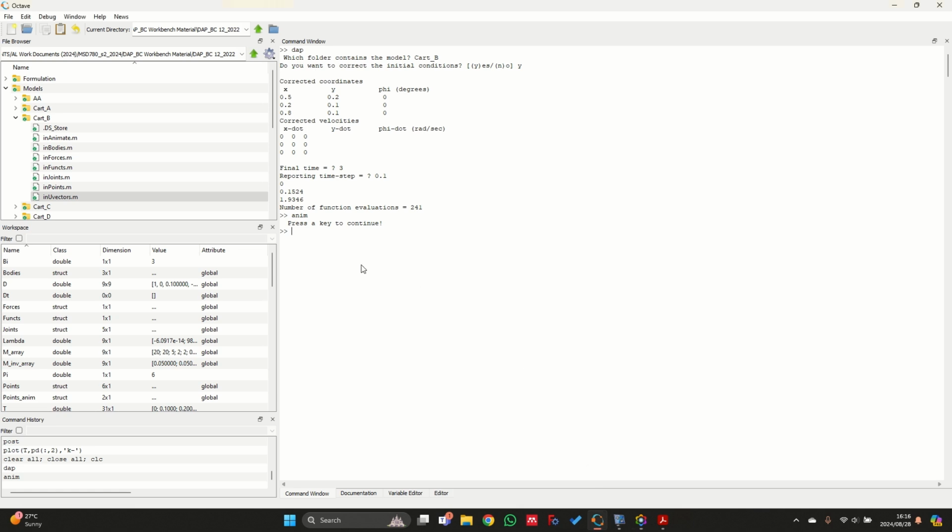So to do this, we're just going to run post, and just to reiterate what we said in the mind map as well, we expect to see a change in the angular velocity from 0 to -2 pi radians per second after 2 seconds, and then for 2 to 3 seconds we expect to see a constant angular velocity of -2 pi radians per second, or -6.28 radians per second.